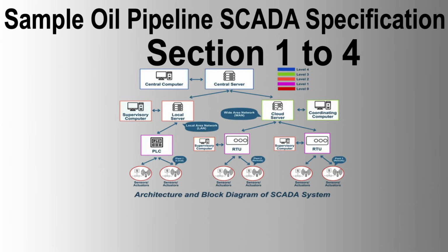Section 5, RTUs. Design requirements. Advanced Intelligent Device for integrated control, supporting multiple protocols and Ethernet ports. Performance, scanning times and time-stamped inputs. Services included configuration, programming, and diagnostics. Construction and wiring, suitable enclosures, labeling, and earthing.